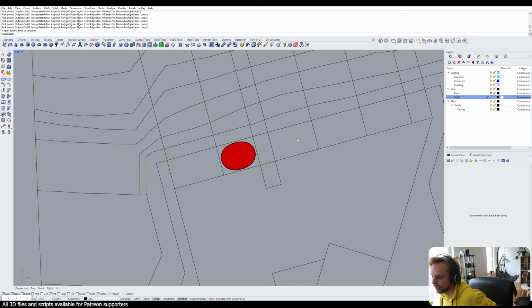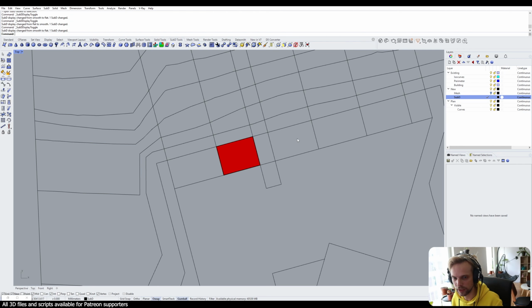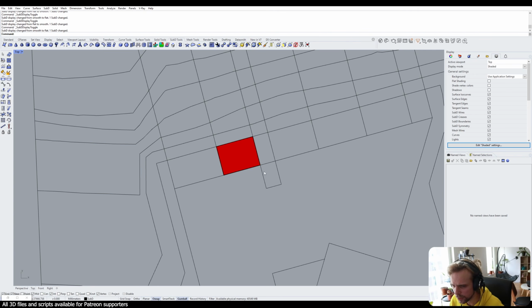So this little polygon is created. If I hit the tab button, you can see that it changes. What you see here, the rectangular view, is a control polygon, and if I hit tab, that's the smooth version, that's the actual geometry of the sub-D. So 99% of the time we stay in the control polygon view, right? So this rectangular view.